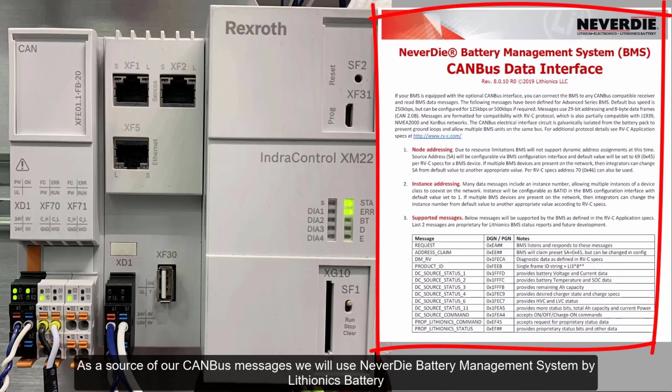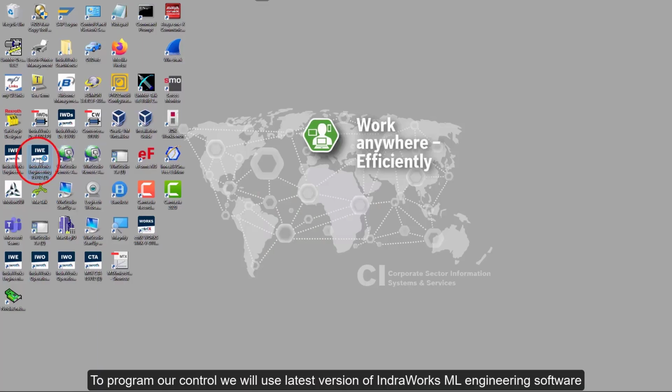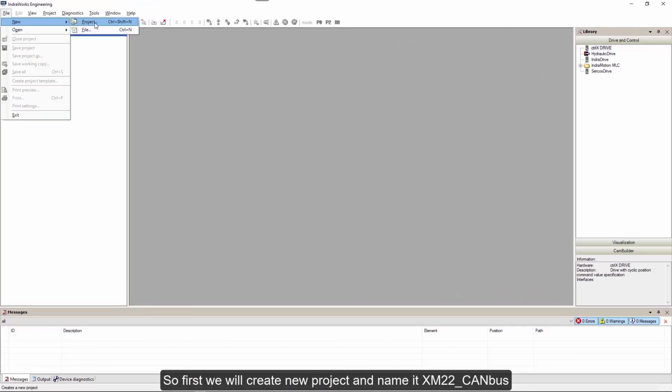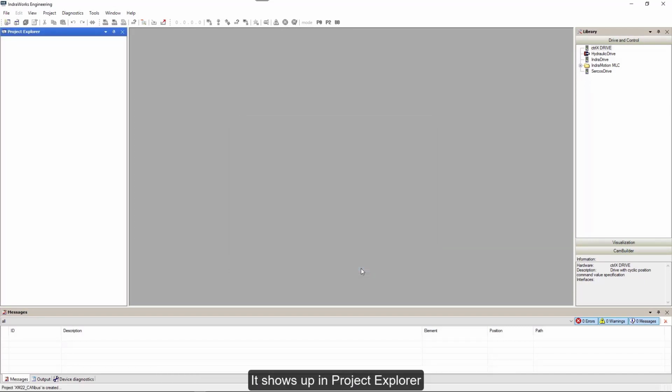As a source of our CAN bus messages, we'll use the Never Die Battery Management System by Lithionics Battery. To program our control, we'll use the latest version of IndraWorks Engineering software. So first, we'll create a new project and name it XM22 CAN bus. It shows up in Project Explorer.